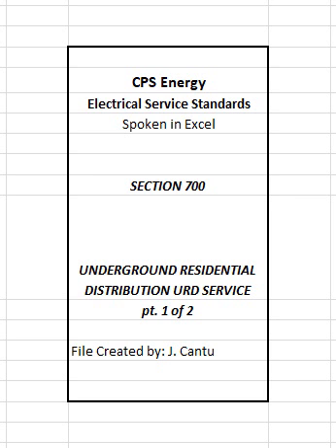Customer shall coordinate with the CPS Energy customer service representative to have all necessary inspections before covering or pouring, refer to helpful numbers listed on the inside front cover page. 3. Service laterals in conduits furnished and installed by CPS Energy. The service lateral typically is installed from pad mount transformer terminals or from secondary enclosure directly to the meter socket on the building or structure, refer to Articles 704 and 705.